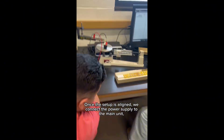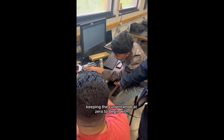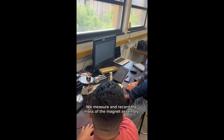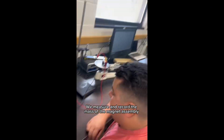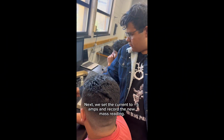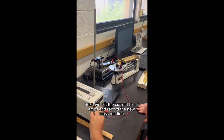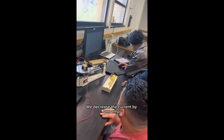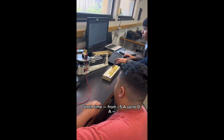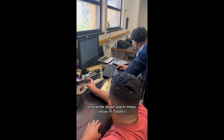Once the setup is aligned, we connect the power supply to the main unit, keeping the current knob at 0 to begin with. We measure and record the mass of the magnet assembly when no current is flowing. That's our baseline mass. Next, we set the current to -5 amps and record the new mass reading. We decrease the current by 1 amp each time from -5 A up to 0 A and write down each mass value in Table 1.